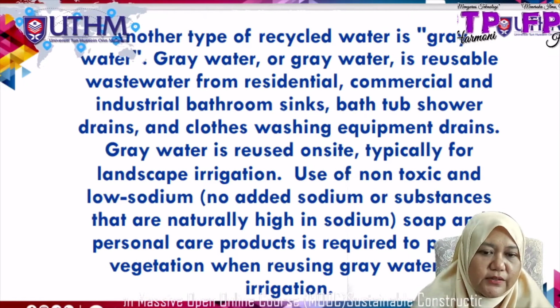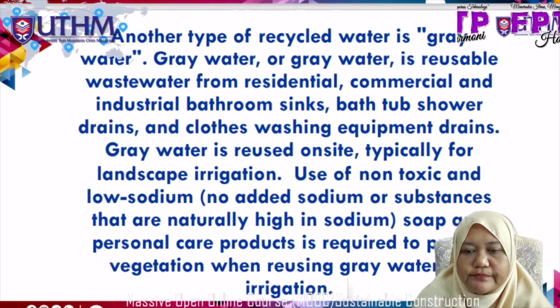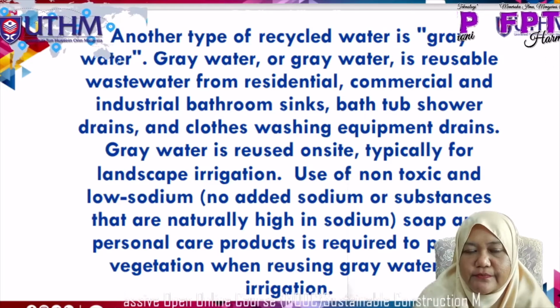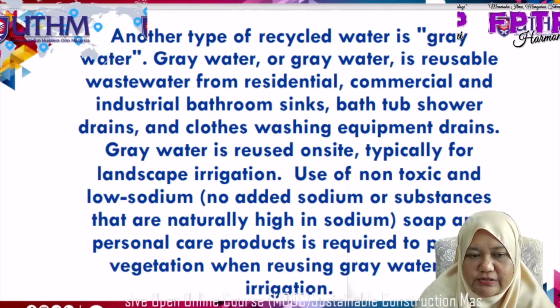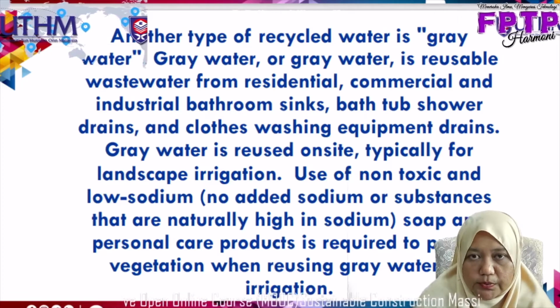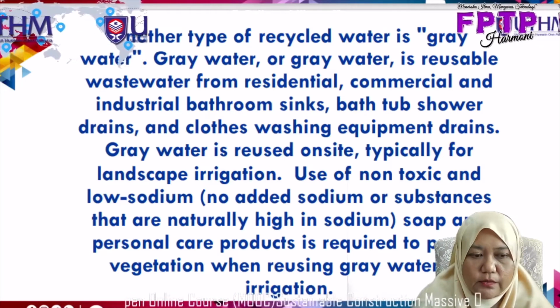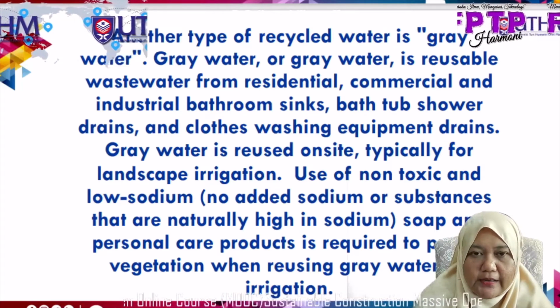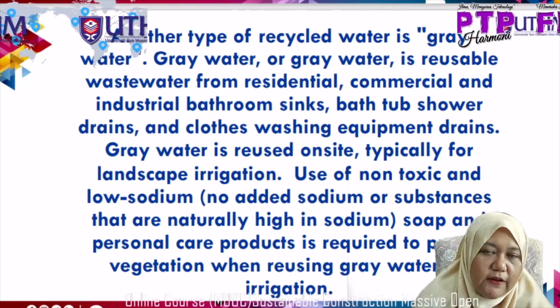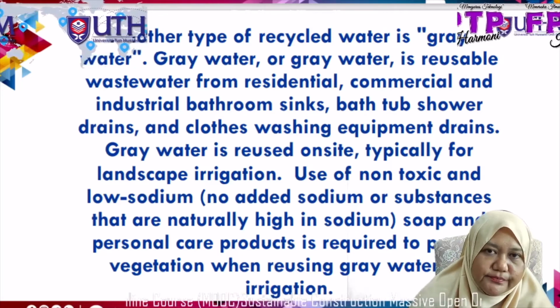Use of non-toxic and low sodium soap and personal care products, with no added sodium or substances that are naturally high in sodium, is required to protect vegetation when reusing grey water for irrigation.